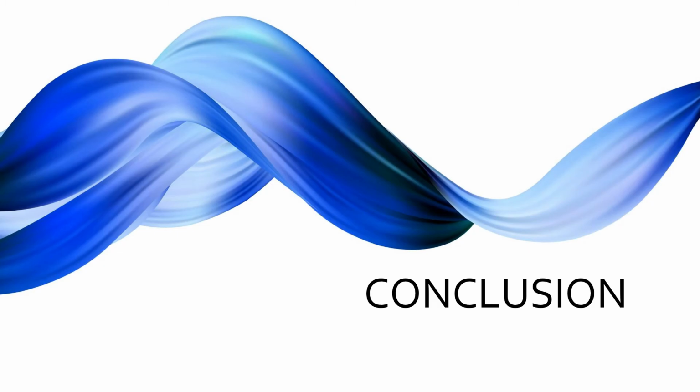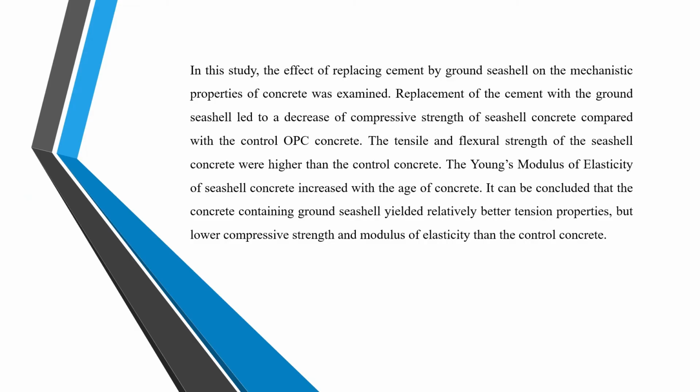Conclusion. In this study, the effect of replacing cement by ground shells on the mechanical properties of concrete was examined. Replacement of the cement with the ground shell led to a decrease of compressive strength of shell concrete compared with the controlled ordinary Portland cement concrete. The tensile and flexural strength of the shell concrete were higher than the controlled ordinary Portland cement concrete.